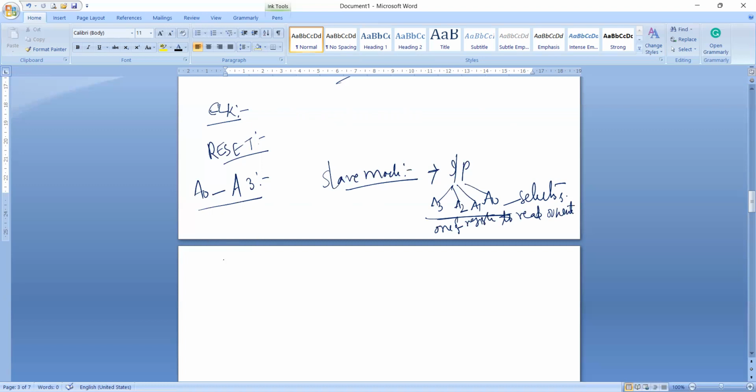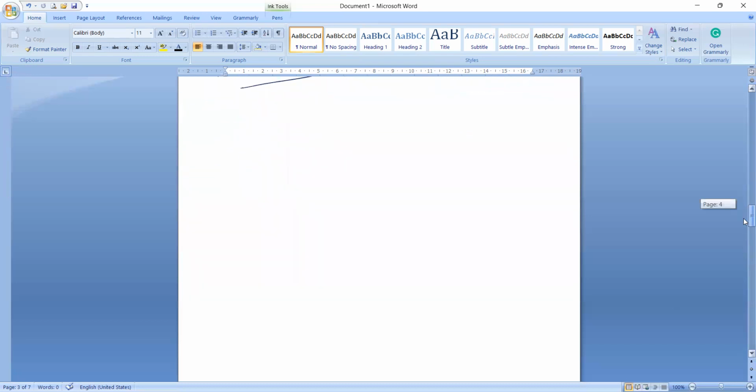In master mode, what happens to the A0 to A3 lines? In master mode, they are the four least significant memory address output lines generated by 8257. These are the input lines under slave mode. Very important, let's try to explain all the points.